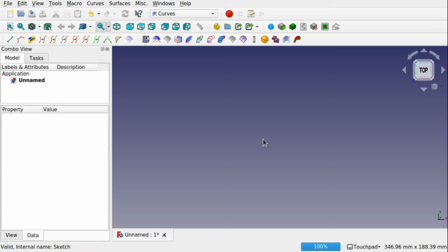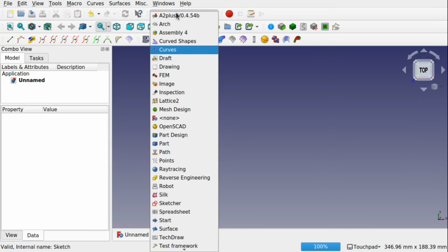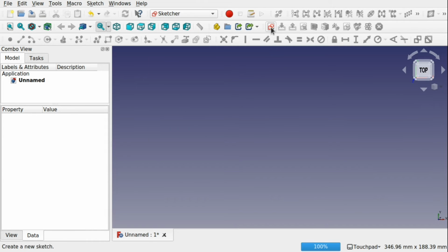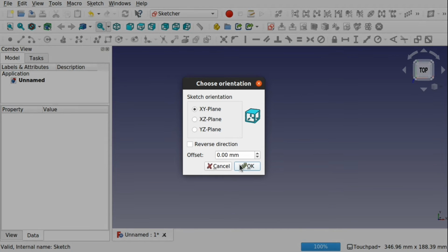Let's say I wanted to create a bicycle seat. We can use these tools to actually create that bicycle seat and affect the curvature of that seat at different parts. So we first need our shape. So I'm going to come into the sketcher and I'm going to create a new sketch. Go on the XY plane.